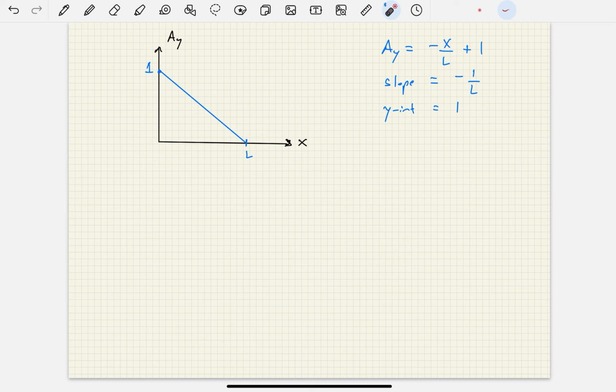So this is a lot more efficient though. Notice that we did not have to do equilibrium processes over and over again, okay? In this case, we wouldn't have really had to do method of sections because we're just getting AY. We would have just had to do AY calculations over and over again. But when we looked into this topic for a truss, we had to do method of sections over and over again because the effect we were interested in was a member force, okay? So again, we're taking this concept and applying it to beams now.